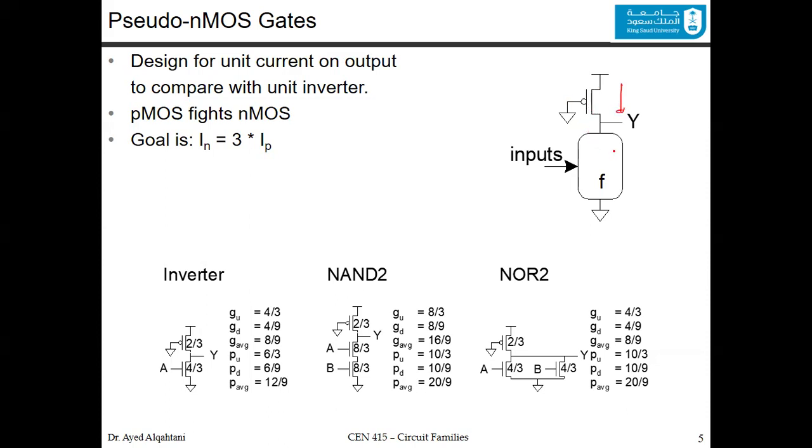Now, the circuit that you want to design, you design it over here in the pull-down circuit or the pull-down network. And in the pull-down network, as we discussed before, you'll find the function. Let's say that the function is y. To get the function, it should be something bar. So we need to make sure that you have this bar, and then you put whatever you have there, you design it in the pull-down network, and that's it. No duality anymore.